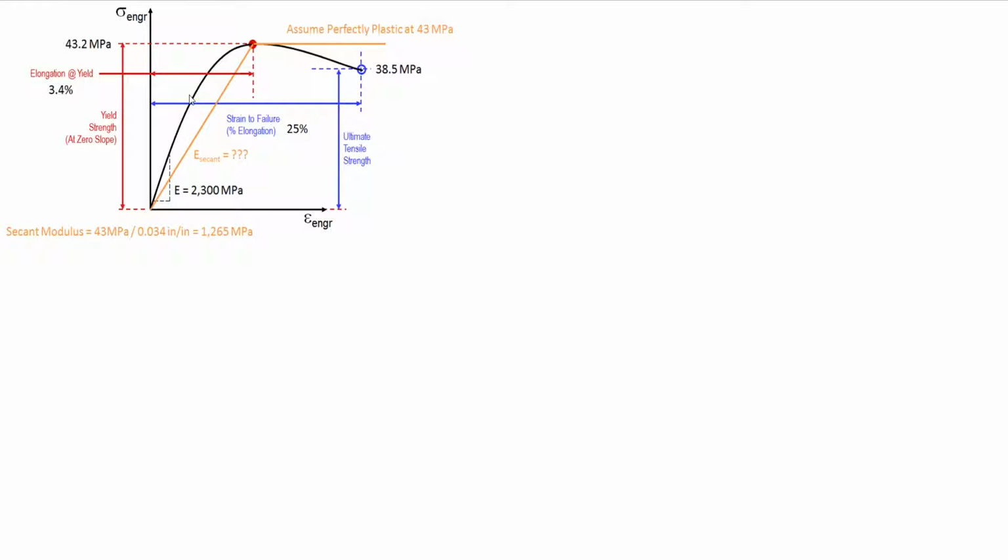And then according to this result, we could make the assumption that it is a brittle or a ductile material. A brittle material means that it has a low percentage strain to failure, and a ductile material means it has a high percentage of strain to failure. So I usually make the cutoff around 10%. If it's 6% or lower, and sometimes in between up to 10%, it's a brittle material, and then above 10%, it is a pretty ductile material. So ABS is a very ductile material, right?